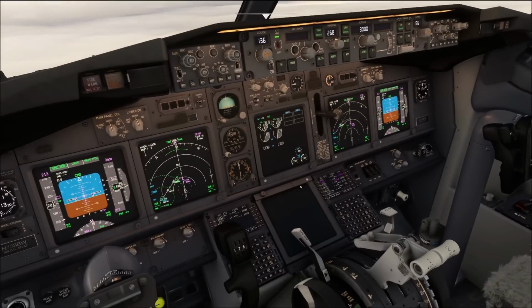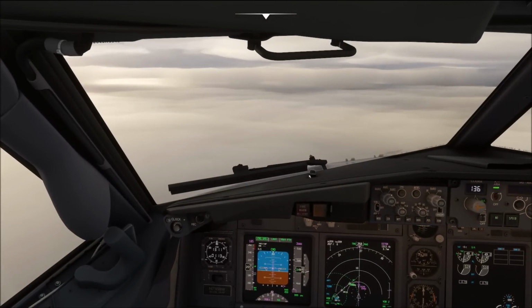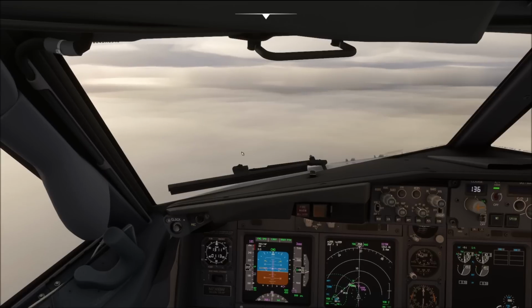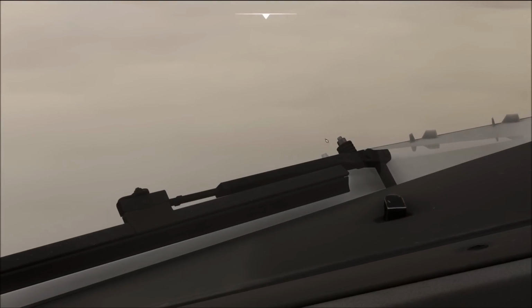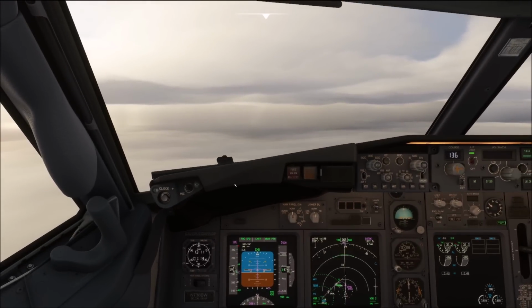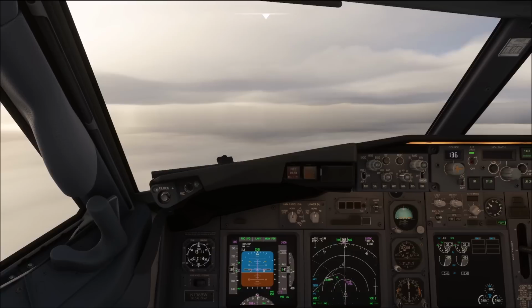And what we can do for that is to have a look at the wiper up here. When ice accumulates on your airplane, you are going to see it on the wiper. In real life, you will mostly see it over here at the screws and on the bottom of the actual wiper blade. Due to limitations in Microsoft Flight Simulator, it will be the entire wiper that is going to show you ice effects. Nonetheless, when you do see some ice building up here, chances are you will have icing on your wing as well, and therefore want to use anti-ice.